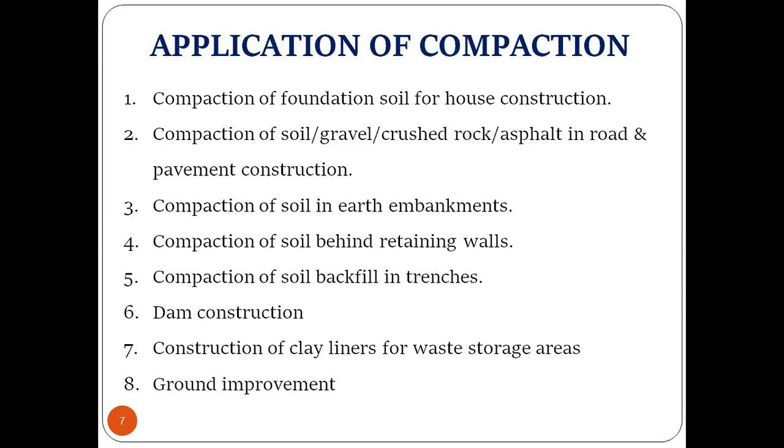And then in dam construction, if I am going to do any dam construction, then we have to consider a stronger soil, right? We have to compact it and provide a denser soil so that it can bear any load coming on it. And construction of clay liners for waste storage areas. If you have to provide clay liners in a waste storage area, then we have to use compaction. And then ground improvement.